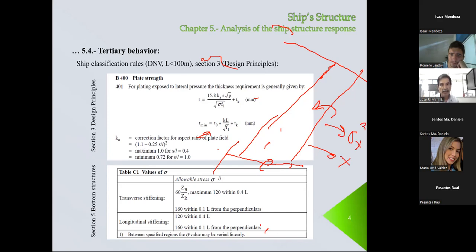This is the tertiary. And in the X direction, you're going to have also the primary stress. So the two are going to combine directly, and that's why you have to think of that. That means you can allow the tertiary stress in the transverse framing system with a lower value than in the case of the longitudinal framing. It's something which is very interesting.